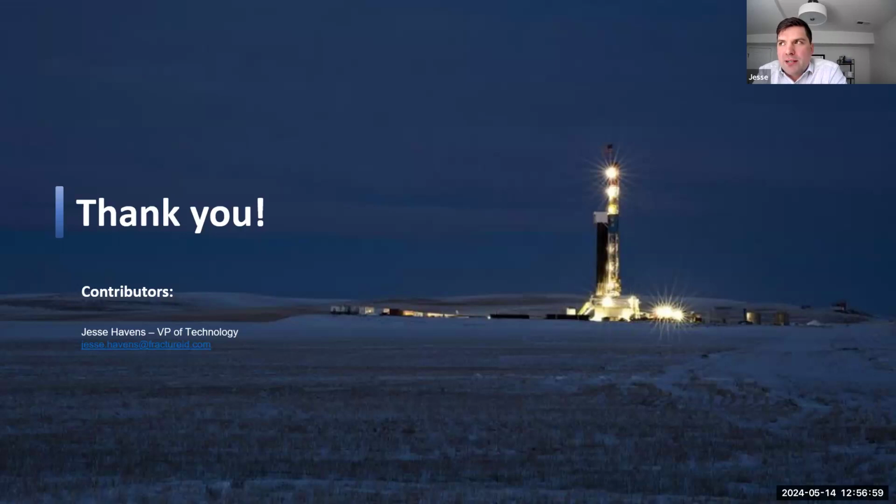The first part of that question was how the various sensor placements affect the signal. It says, how does MSE on rotary versus soft torque drilling vary across the string and on the bit within the BHA?